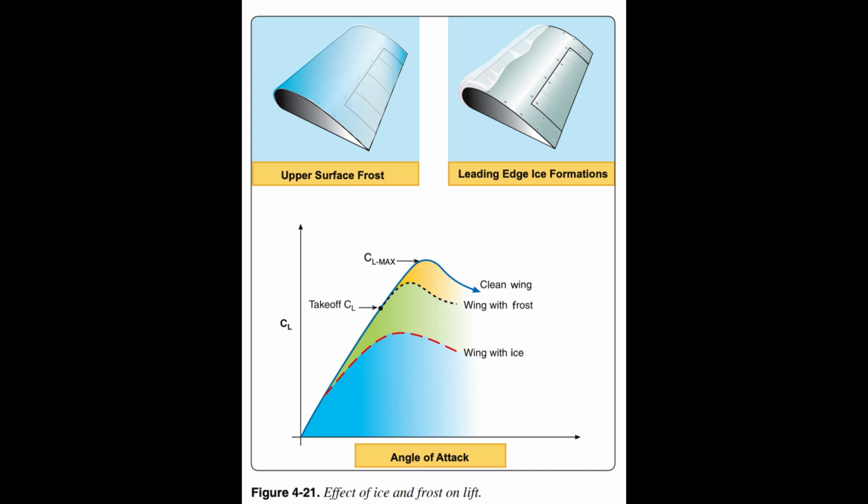Ice can partially block or limit control surfaces, which limits or makes control movements ineffective. Also, if the extra weight caused by ice accumulation is too great, the aircraft may not be able to become airborne, and if in flight, the aircraft may not be able to maintain altitude.